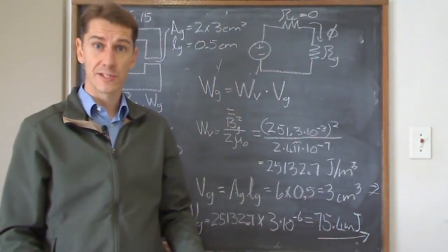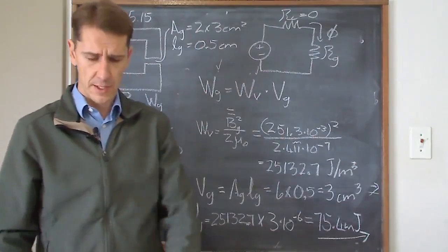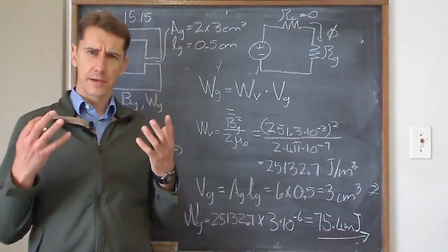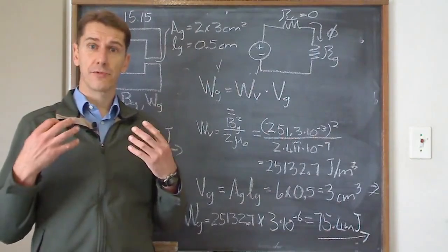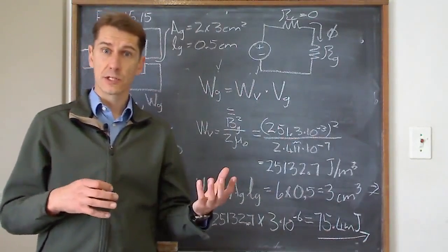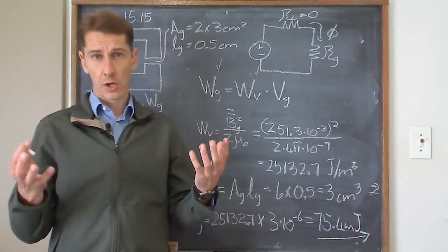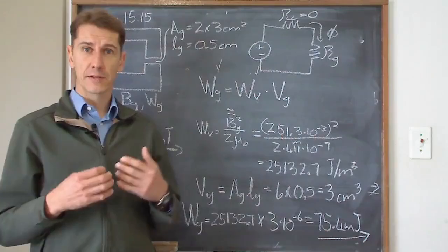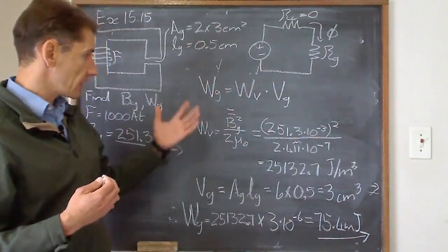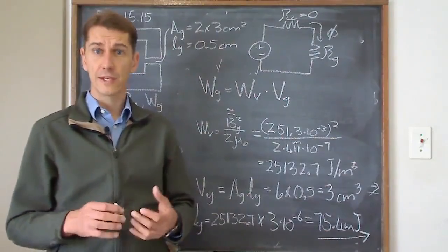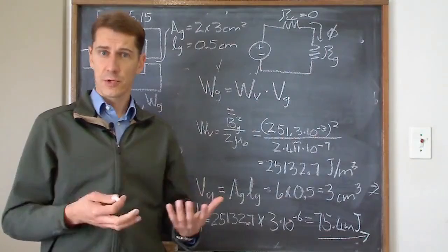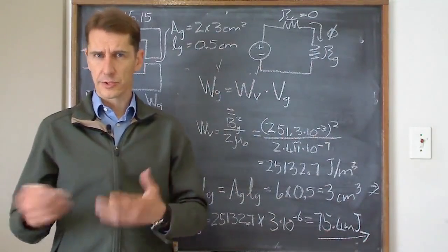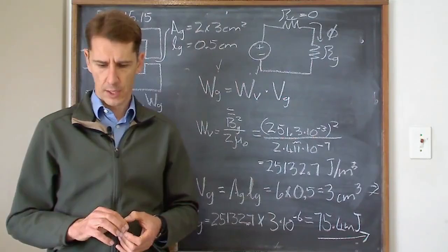And guess what? That's it for this small little lecture on magnetic materials. What I expect from you is the theory bit: know what hysteresis is, know what saturation is, what is hysteresis loss, what is eddy current loss. They combine to form core loss. And with these examples, we actually calculated what the losses in the core are: the energy, flux density, energy stored, hysteresis losses in the core. What we've done in the exercises here, and you'll see in the homework problems what you need to do there, that's what I'm going to expect from you.